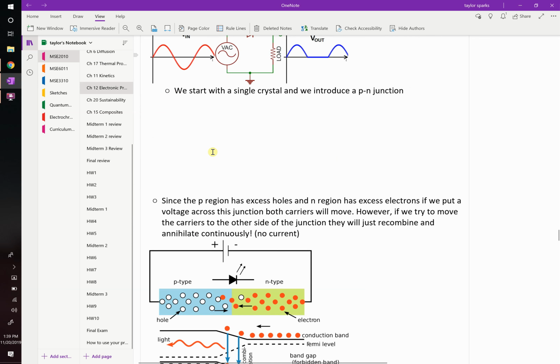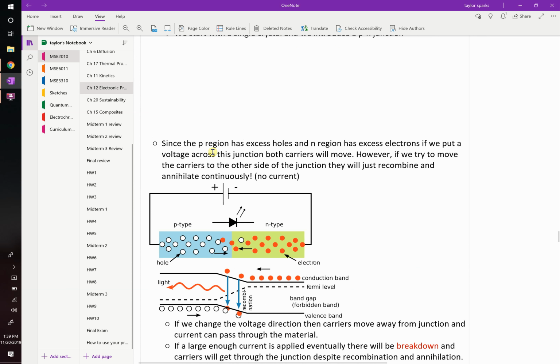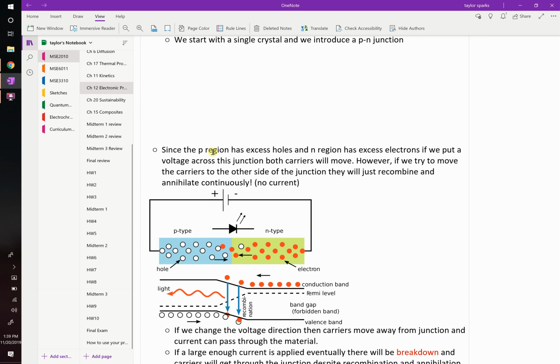It's pretty amazing. You grow a material. I've actually got it right here. You grow a material and you make it, let's say, initially n-type. So when you grow the silicon, a perfect single crystal, you introduce phosphorus in that growth process. So it's a nice, perfectly organized crystal, except that you've replaced some of the silicon with phosphorus. So mostly everywhere, it becomes n-type. You've got an excess of electrons, right? Now what you do is you sandwich that with a material that's p-type.